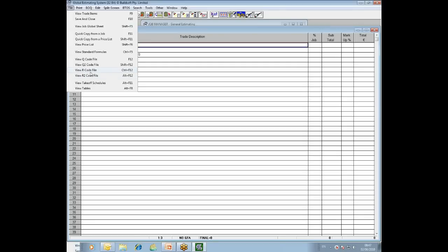into trade packages for subcontract pricing, and the OR2 codes might be used for resourcing individual component parts of rates for maybe an analysis in an accounting system of a bill. That would be commonly what they're used for. But in essence, their use is pretty much similar in that what it allows you to be able to do is resource up a bill or a tender document into an alternative format for analysis, maybe a tender meeting or for subcontract comparison or whatever it might be.